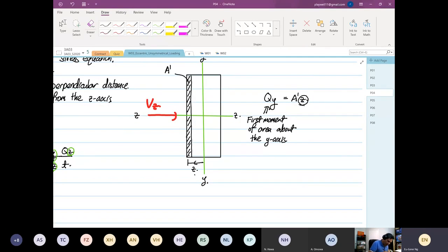If we look at the diagram, the Vz over here, again our shear now is on the x plane, the shear force is acting in the z direction, or the shear stress will be acting in the z direction. The intersecting plane intersects the x-axis. So this will be equal to Vz over Iyy, Qy divided by thickness.